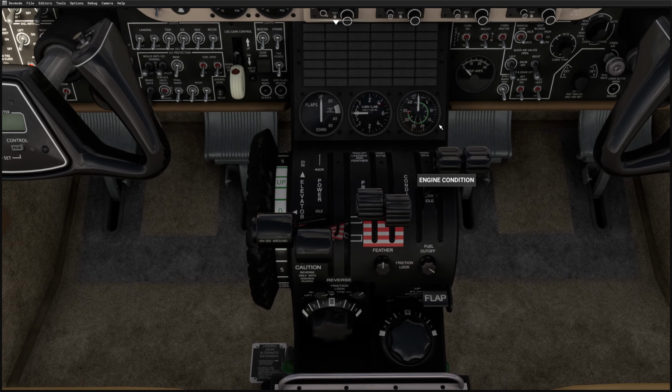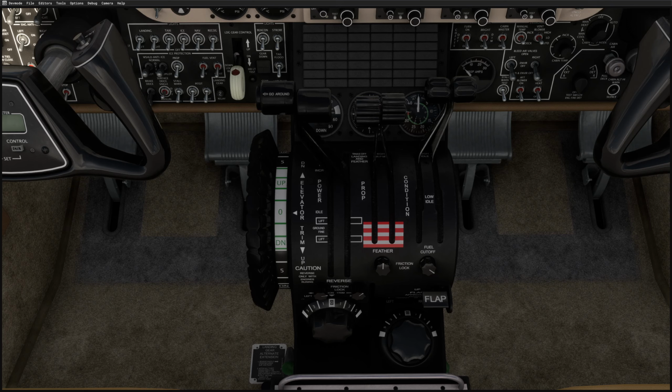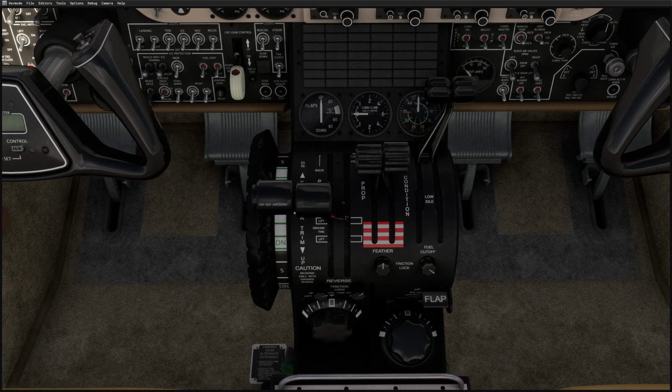There are some gauges up here where we can look at the differential of the pressure and see what's going on, and also we can control the rate of change of the pressure within the cabin. Again, too quick a rate of change is uncomfortable for the passengers, but these are a little tricky to see when we're in flight. Once we've got the levers in position, we cover things up. So on my Stream Deck, I use some gauges, mimicking those onto my Stream Deck, so they're easier to see.